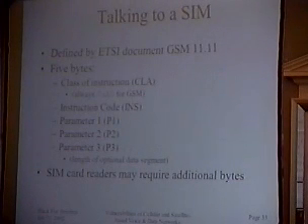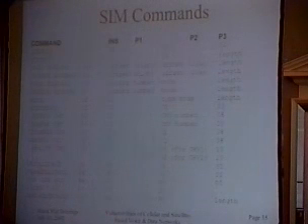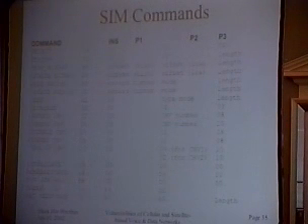Depending on the SIM card reader you're using, there may be additional overhead that you have to wrap around it, a command to get the reader to tell the SIM card to do something. So you send this command to the SIM, and then the SIM is supposed to answer you. And the SIM will come back with information, if there is any that you asked for, and then 2 status bytes. So it's a fairly simple protocol. So for a GSM, this is a set of commands that it will understand and know how to operate.